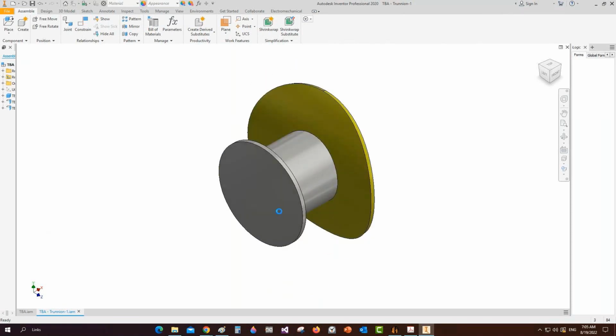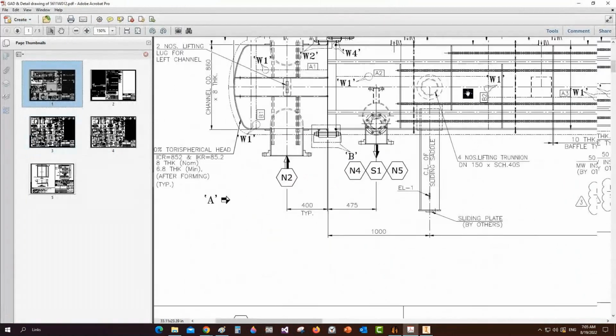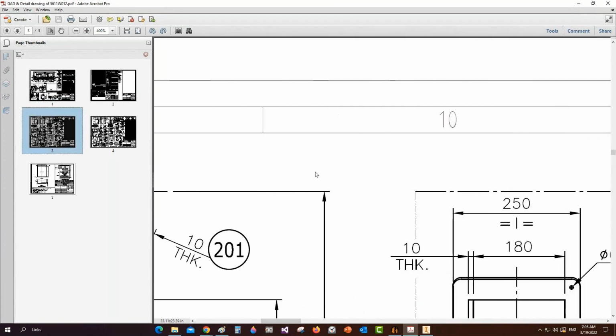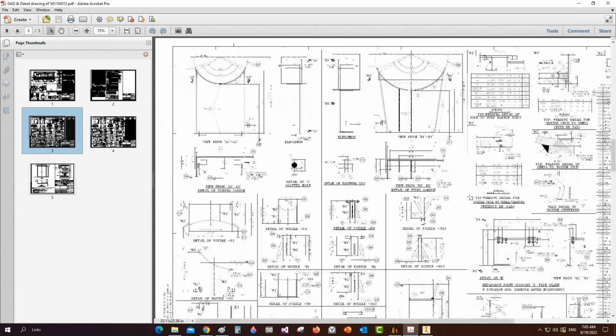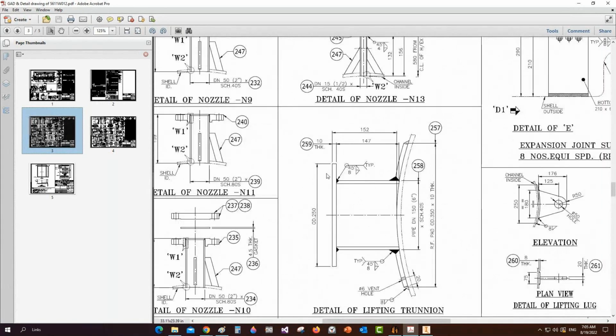Okay, and here I have a note regarding the trunnion, because as per your drawings, when I checked the drawing diameter here, it was 250, which is the end plate diameter, not the rebar diameter as per this detail. If we take a look at this detail here, yes, that one. The drawn diameter on the GA was 250, not 350.